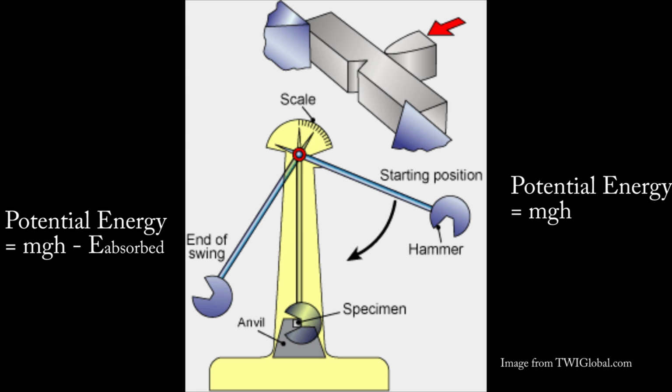So the physics of the Charpy impact energy problem is actually pretty straightforward. You start out with a little bar with a V-notch in it, and you can see that up top. And you hit it with a pendulum. Now the pendulum has potential energy associated with it: mass times gravity times height. And if this pendulum were to swing freely in a perfect world, it would just end up on the opposite side of the swing and reach the same height.